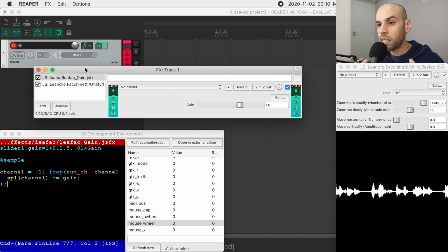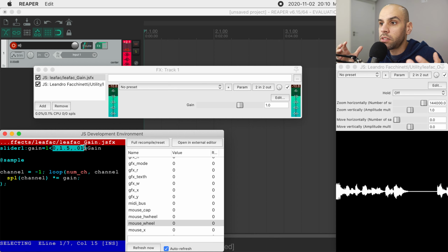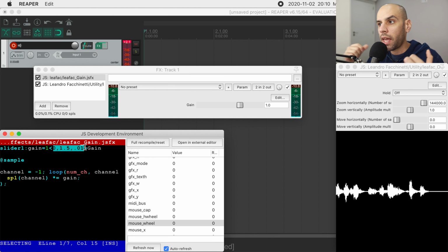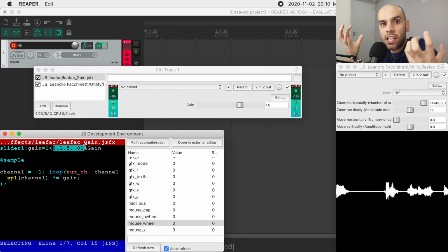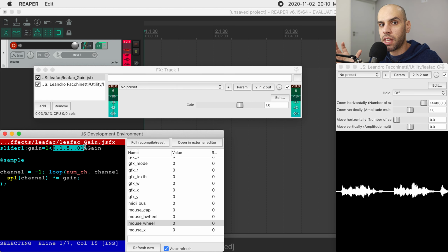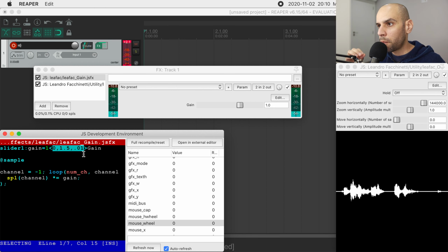So anywhere, when you're working with audio, anywhere you're changing the gain or the volume of something, you think in terms of dB. So we need to be able to transform between this unit of measurement, which is amplitude multiplication factor, and dB. We need to think about the relationship between the two, because they are units of measurement of more or less the same thing in the universe. They're just measuring the thing differently.